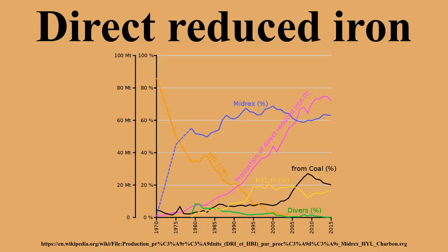Problems. Directly reduced iron is highly susceptible to oxidation and rusting if left unprotected, and is normally quickly processed further to steel. The bulk iron can also catch fire since it is pyrophoric. Unlike blast furnace pig iron, which is almost pure metal, DRI contains some siliceous gangue, which needs to be removed in the steel-making process.